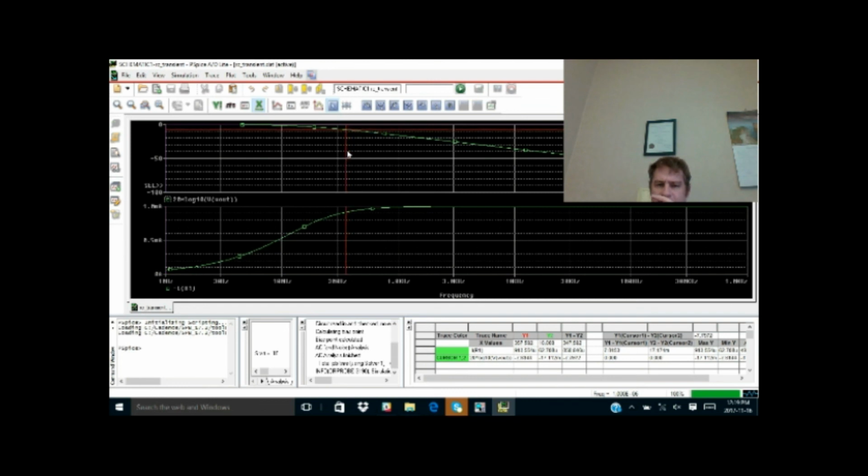This is -8 dB. We're going to make it go here. -3 dB. Our -3 dB is at a frequency of 159 hertz. So we should double check that it matches theory. So there we go. We just created ourselves a frequency domain simulation and a frequency domain analysis.